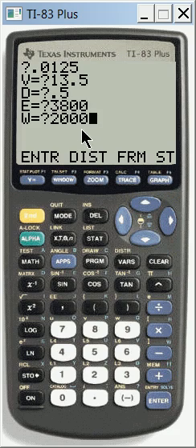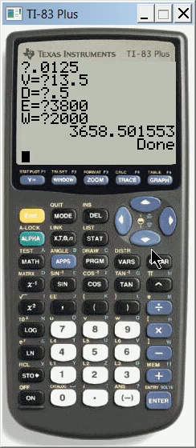And this is where in class it kind of stumbled on us. We hit an enter here. And that sounds reasonable. If you think about it, the energy grade line is going to start at 3,800 and go to around 3,500 if this is a freely flowing system. That means halfway down it's lost about half of its energy.